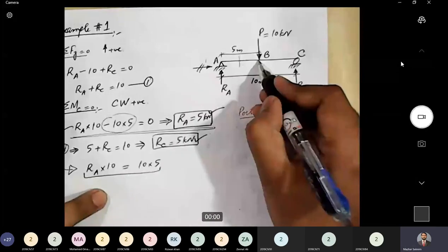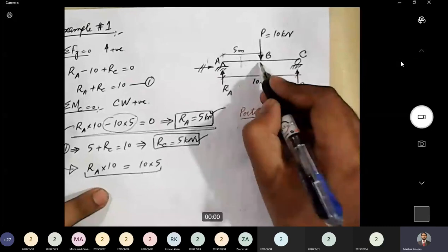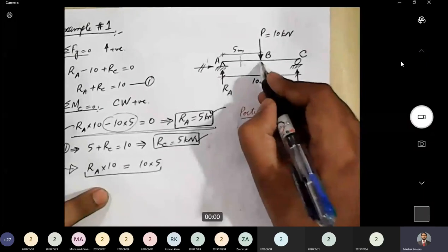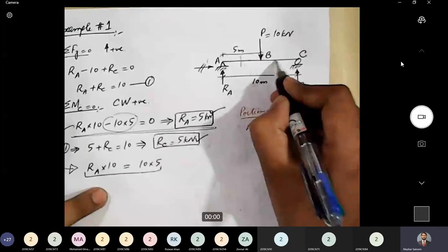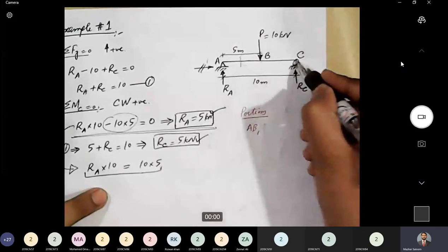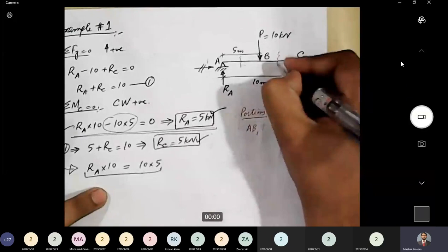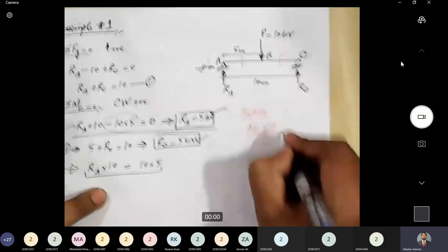because at point B we have another applied load, so we have a change. So we need to define another portion after point B, and that portion will end where we see the next change. So from point B, at what location do we see the next change? It is at point C. We have a support and a reaction. So there will be a second portion BC. So this is our second step.